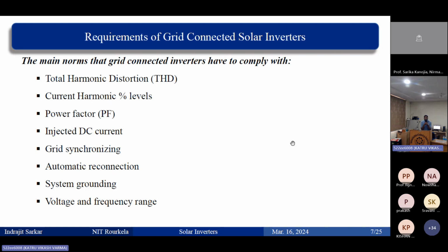Now, when I first studied inverters in my BTech classes, the first thing I always thought about was how we can generate a sine wave. An inverter always operates either in square wave mode or PWM mode. So there is no way that you can make it a pure sine wave. It is not possible. Okay. So what you need to do is use filters, right?